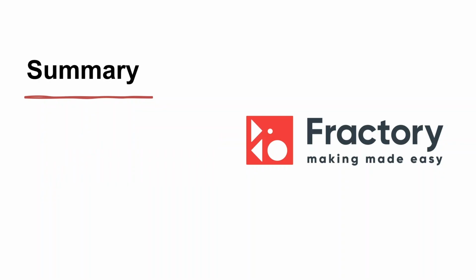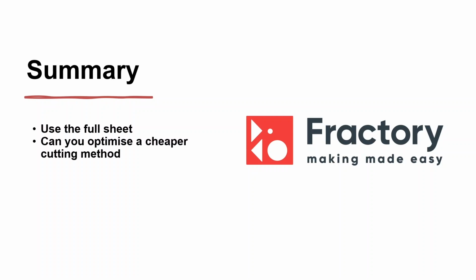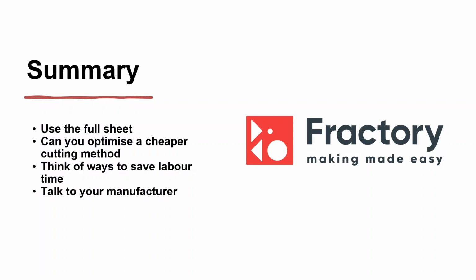So just as a quick summary, use the full sheet. Can you optimize a cheaper cutting method? Think of the actual people who are going to be making the parts, what labor they're going to have to go through, and try and visualize if there are maybe quicker ways that they can do it, and talk to the actual manufacturer that you're planning on working with to try and save some costs.